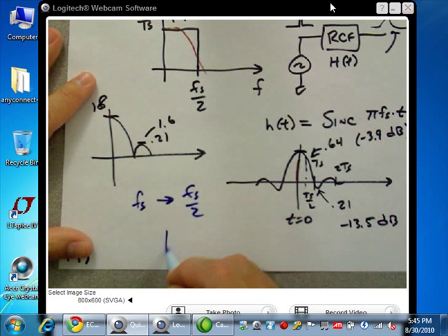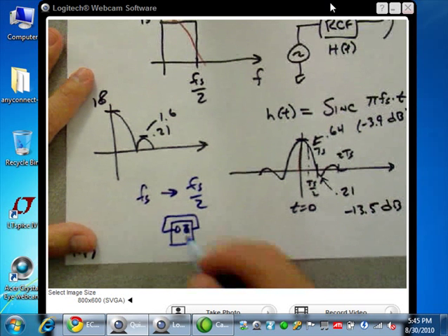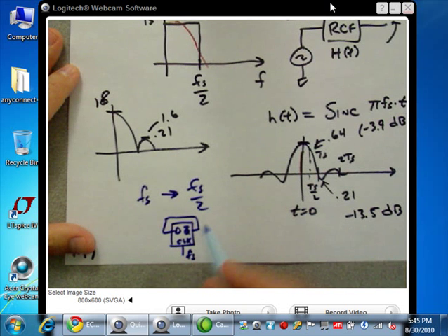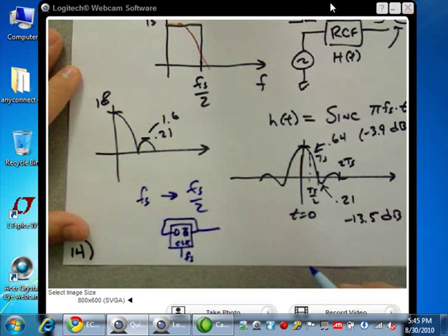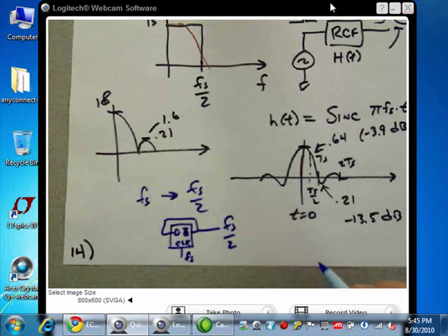Just this, right? A D flip-flop, feed Q bar back around, clock this with f sub s, it divides by 2, and this output becomes f sub s over 2. If I wanted f sub s over 4, I'd use 2 of them, right?